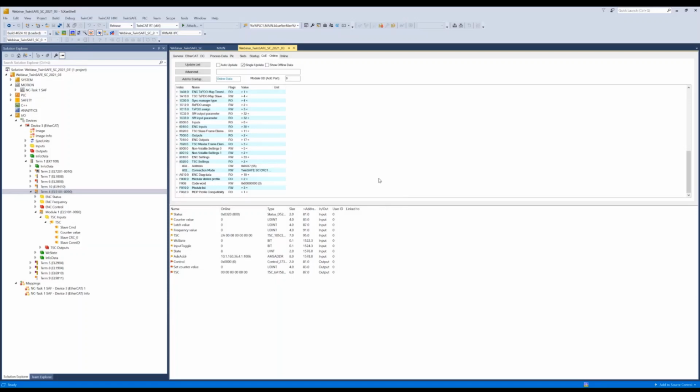So we don't have any possibility for the product identification out of the hardware. We need to add this by software address. That's why you always need to put in the address here, and just remember the address because you will need it later on inside the safety logic.